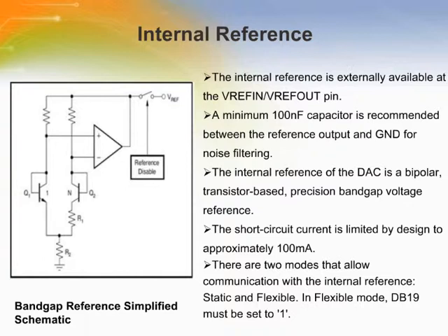To enable the internal reference, write the 32-bit serial command after performing a power cycle to reset the device. The internal reference is switched off in default mode. In the default mode, the internal reference is powered down until a valid write sequence is applied to power up the internal reference. If the internal reference is powered up, it automatically powers down when all DACs are powered down in any of the power down modes.